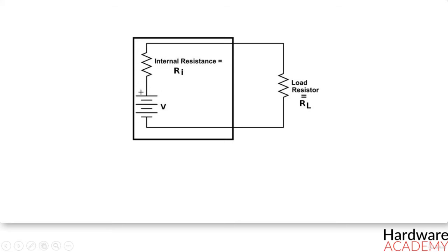This is proven by Ohm's law. According to Ohm's law, voltage is dropped across circuit elements according to the formula where the voltage is equal to the current times resistance. If a voltage source has zero internal resistance, it can drop all voltage across a load and none will be wasted internally. This is 100% power efficiency, and this is an ideal voltage source.